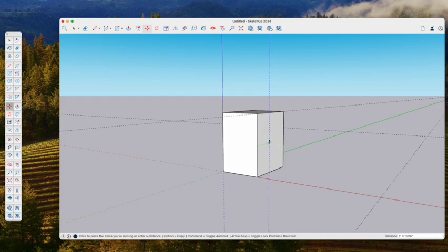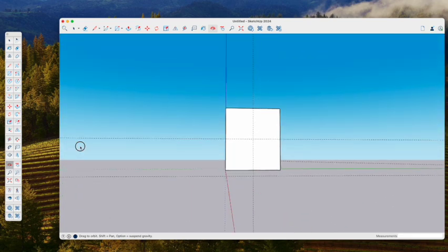So we went on the green, right? So the green will be the same dimension. Now it's not going to tell me if I'm in this area that I'm at the midpoint, but if I'm up here, it'll pick the midpoint. Now it's black because we're not in the plane, but it's okay because we found that's the midpoint of that line. Pick this guy, hit the move tool. I'm going to grab him there. We're at that midpoint. So now we're ready to make our little pipe. You can see that's pretty much in the center.